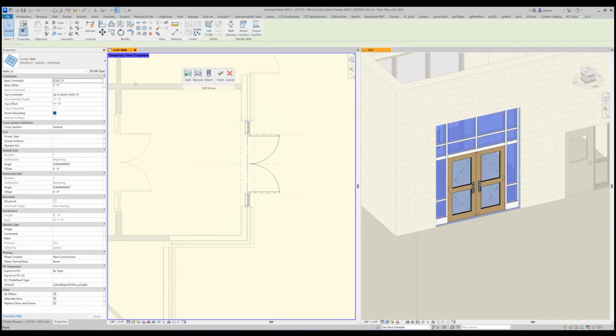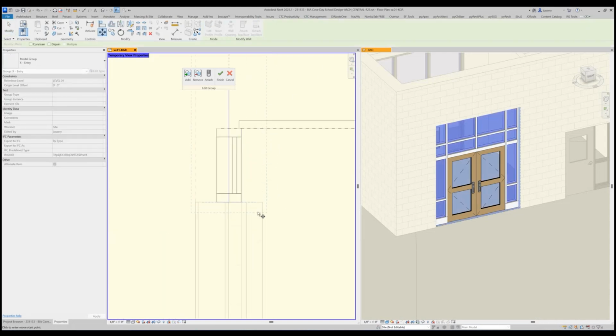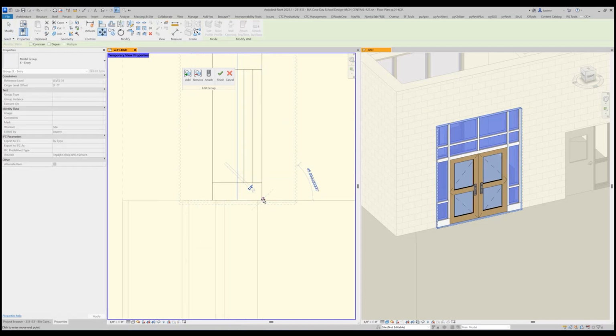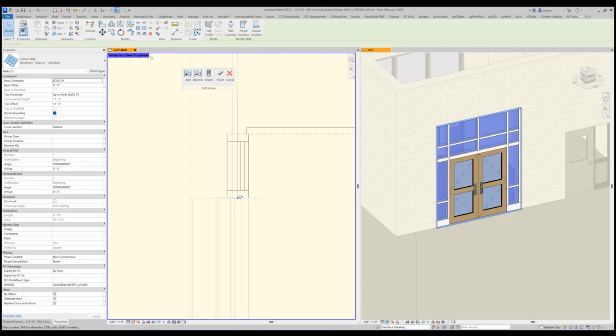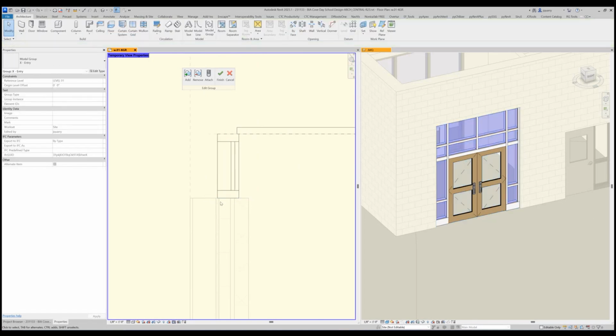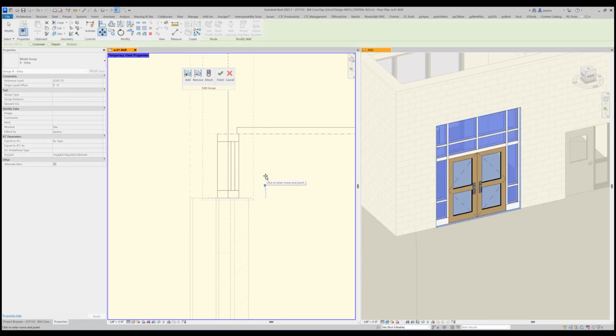Now let's go inside of here for a second. We know that most exterior windows and doors, depending on what this detail is going to look like, usually you would take this CMU. I don't know if you'll have a return on it. Chances are probably not. Chances are this usually wants to be out here. Usually 2.5 inches is where I start from the exterior side of the masonry. So let's just do 2.5 inches and see where it goes. It's not quite there because we want it to cover this entire part right here, so let's go another 1/2 inch and see where that goes.